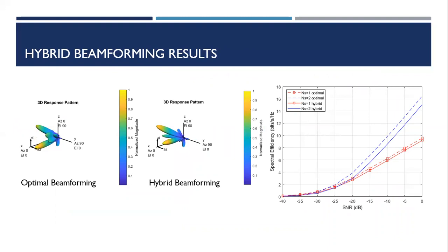So within optimal beamforming, we are usually using the entirely analog system or digital beamforming system. So within analog system, we have a single wave that is fed into all the elements of the antenna, but they are differentiated from one another using the phase difference. So the wave is same, but the elements are separated from one another using the phase shifters. So analog beamforming does not require robust hardware because there is only single wave generation, and they are phase shifted in order to direct the beam in a particular direction. But the drawback of this